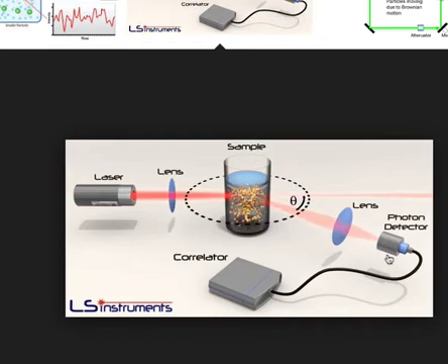So there is a sweet spot for concentration that we'll utilize. This is showing one laser. Sometimes there are two lasers, and usually multiple detectors. What will happen is the laser hits the particles, the laser light is scattered and picked up by the various detectors. The laser will fire separately in sequence, and you'll get data on information that way.